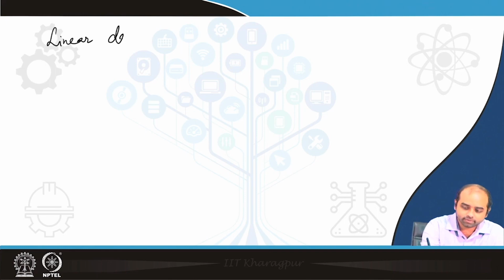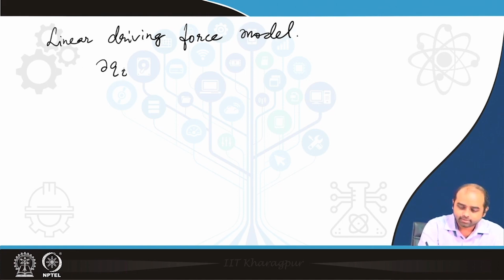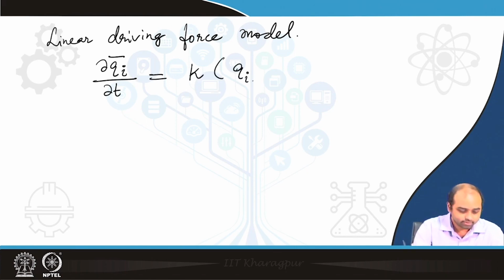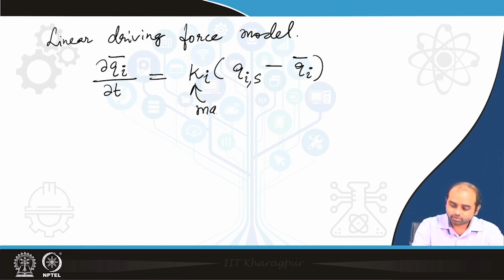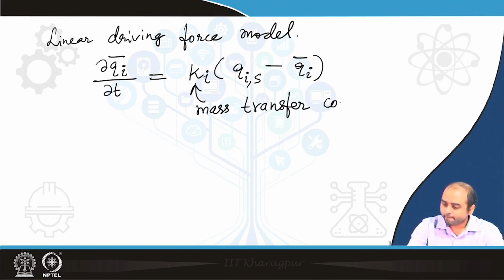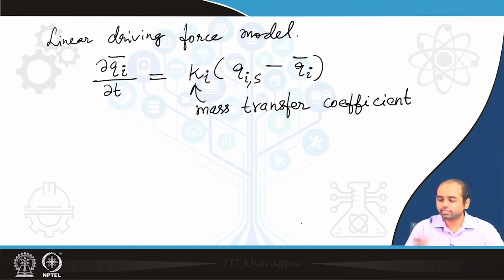So, this linear driving force model tells you that the rate dynamics of the adsorbate concentration is given by this mass transport model where this k is the mass transfer coefficient of the adsorbing species in the bed.